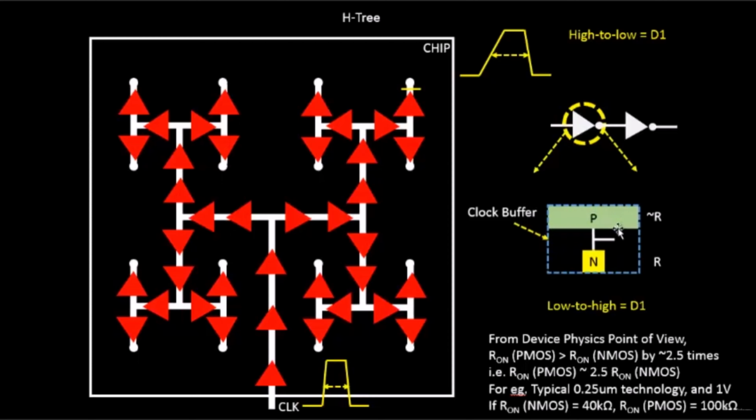So those problems are there, but these are manageable problems because we don't have any other solution for high speed circuits. So we have to restrict ourselves to this solution with some penalties, basically two penalties. One is the area penalty and one is the clock power penalty. Again, the clock path is the one that consumes 75% of the chip power. So this is again a risk that we are taking.